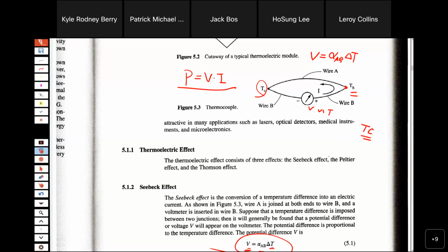The thermocouple does not need any source of voltage. It generates millivolts with the temperature. So we measure the voltage, and the calibration obviously is needed, millivolt and temperature calibration. Once you calibrate it and measure the voltage, you can read the temperature. That's the thermocouple. Wow, beautiful.